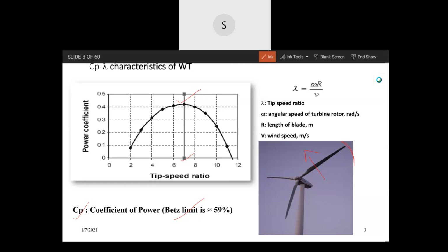And the flow has to, like any other power plant, say a hydropower plant, a thermal steam power plant, a gas power plant. In all these cases, the turbine is working in a fluid. So here also, it's a fluid. It's different from gas slightly, much different from water and steam. The density is quite different. The density is much less here. Otherwise, the flow has to continue, and that is why the full extraction of power is not possible.